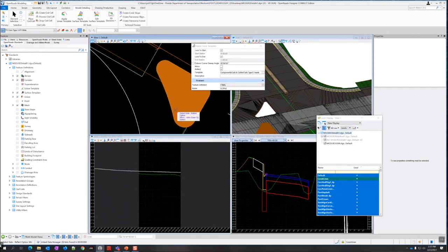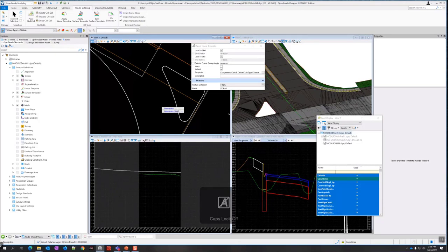So with this linear template, it's a lot like a quarter template, except you can flip it to the other side. You also have the option to mirror it if you want to double it up. Let's say you have it running along something that's like a center line. You can even have it do the two halves of a short roadway or two halves of something. So just make sure the orange is selected on the inside of this, so the curb is going towards the inside. And then it asks for the exterior corner sweep angle. I'm just going to accept the default on that. You can give it a description if you want. I'll just call it right turn island.